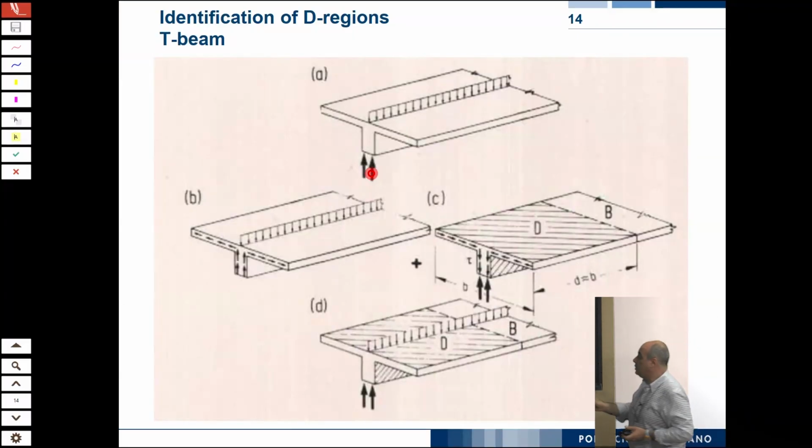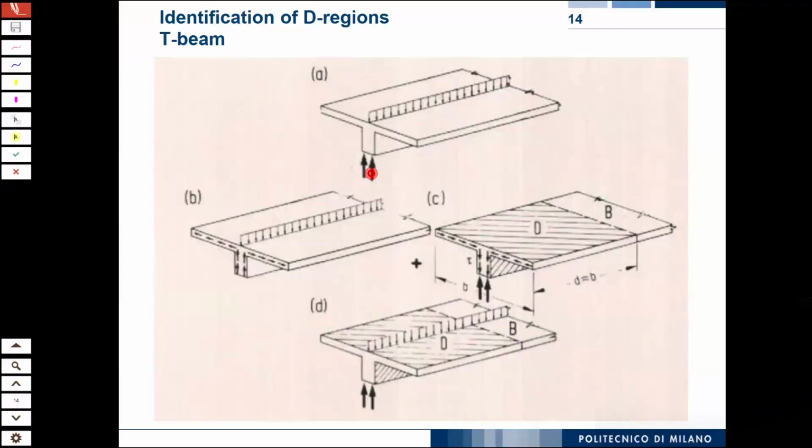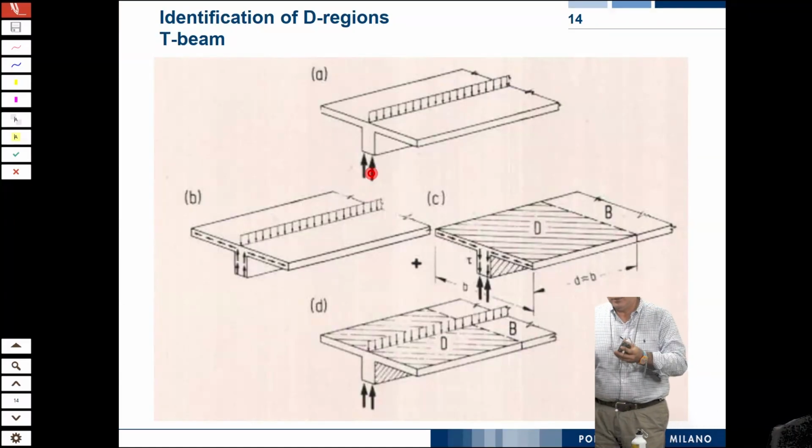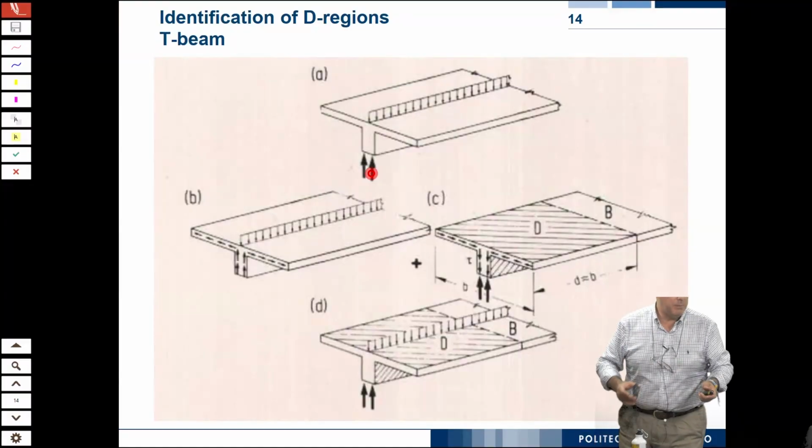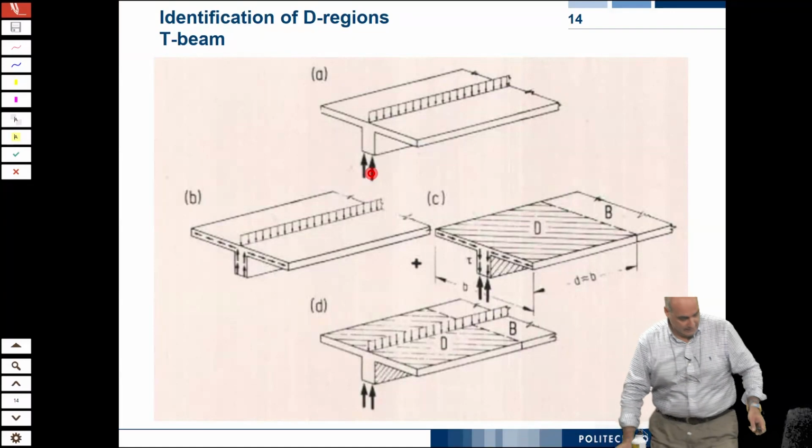Well, the issue is that if you imagine that you have a beam here, then a large slab field, and then another beam, you may not say that the whole width of the slab is collaborating, because the diffusion of the stresses is limited. And in the codes, you find some simple relationships that tell you how wide the collaborating width of your slab is, so which part of it you can consider to be part of the beam, and which part of it you have to design separately.